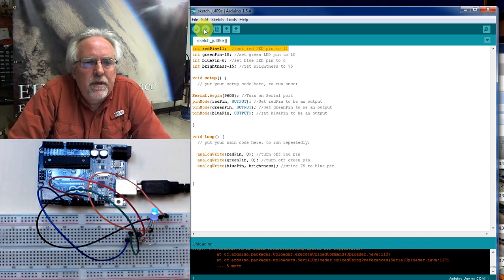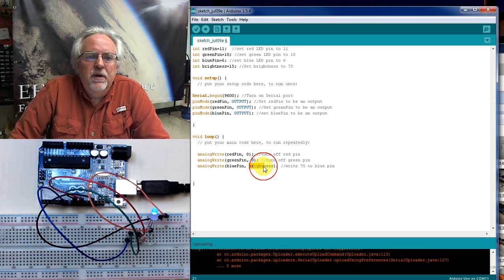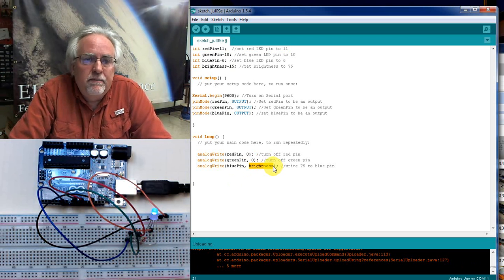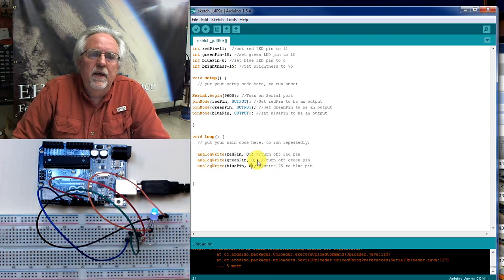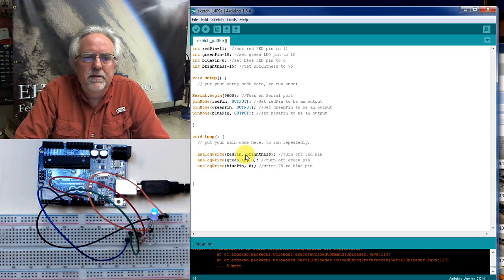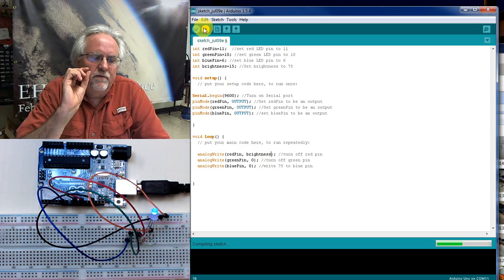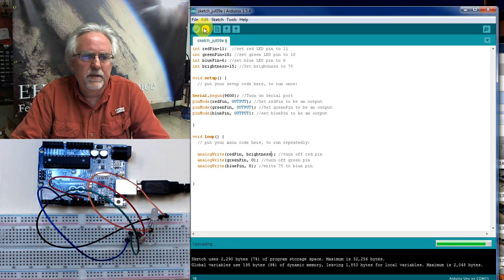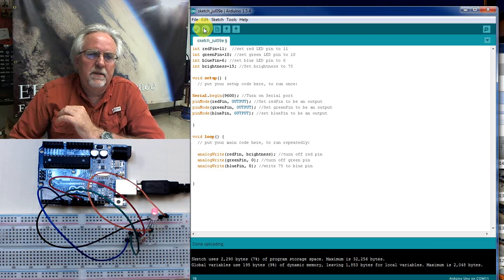Okay, well let's say that we wanted to turn it red. What would we do? Well, we would come in and do I want any blue in my red? No, I don't want any blue in my red, so I'm going to analog write the blue pin to 0, and I would need to take the red pin to brightness. Okay, and the brightness is 15. So this is just a very small voltage that I'm putting on there. I'm barely turning it on so that you can see it nice and good on the camera. Okay, you can see that that turned red.